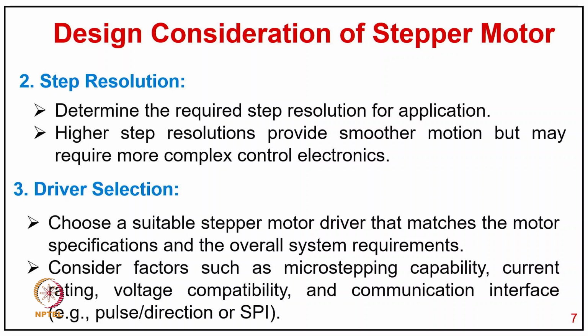Determine the step resolution required for the application. Higher step resolution provides smoother motion but may require more complex control electronics. And third is the driver selection. Choose a suitable stepper motor driver that matches the motor specification and the overall system performance, and consider factors such as microstepping capability, current rating, voltage capability and communication interface like pulse and direction or SPI.